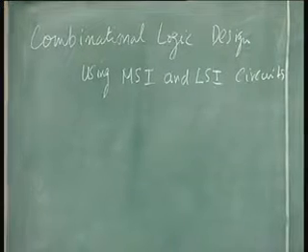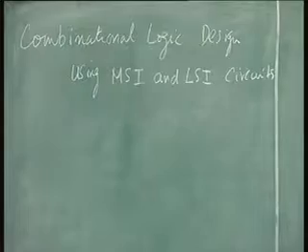Whether it's a full adder, a 4-bit adder, a decoder, a priority encoder, what is that we talked about? The parity checker, code converter. It's all gates, and what we have to optimize is also gates. So this is sort of common sense. It tells us which gates are required, and which gates are available in the hardware piece I am giving you. I am giving you a hardware piece with gate functional equivalents, and I am trying to design a circuit with them. So how best can I map it?